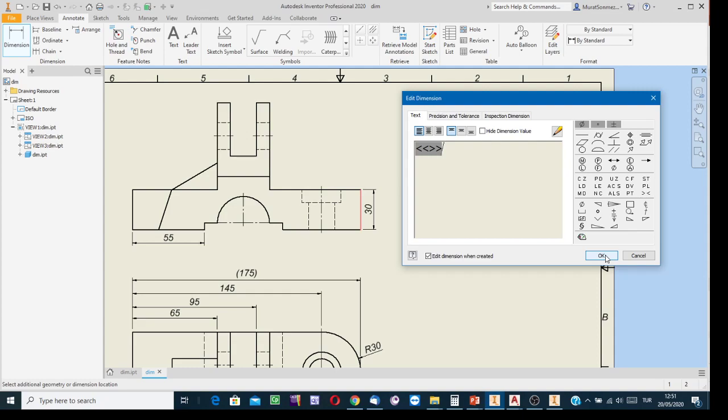It offers either to correct the solid model in size or use the same allowance on showing the dimension of that feature, enforcing Inventor to show not the existing value but the correct value with the underline symbol.